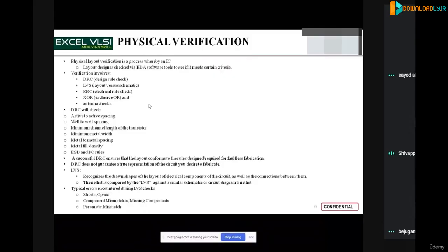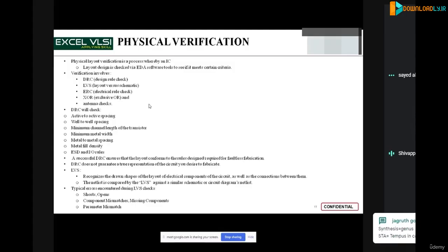And there are specific tools. For example, in the industry, Mentor Graphics Calibre is what is used as a sign-off tool, which takes the rule deck and applies it on the ASIC database, where the physical design is done, and then checks for all these. Basically, all these rules are electrical characteristics, and the constraints they consider during manufacturing are fed as inputs for the ASIC database which is designed.